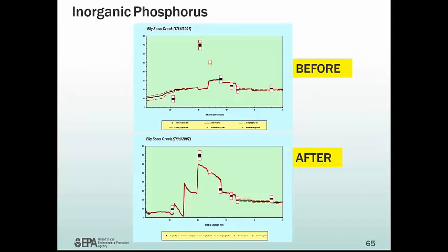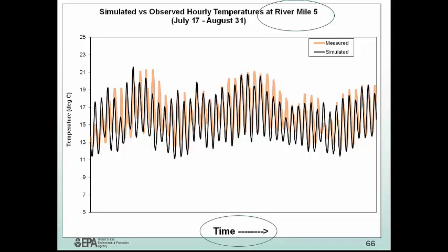Finally, just to point out that perhaps we've done all this work with the dissolved oxygen, we better go back and check all the other things that are linked to dissolved oxygen as we make these changes. So you might do a lot of stuff with dissolved oxygen like we just did. You've got to go back and look at phosphorus, because they're so intrinsically linked. I got so excited there, I forgot how to pronounce intrinsically. Okay, so as part of the DO calibration, we make sure that we're good on all fronts. We're checking all parameters. Okay, so that's my example of a steady state model.